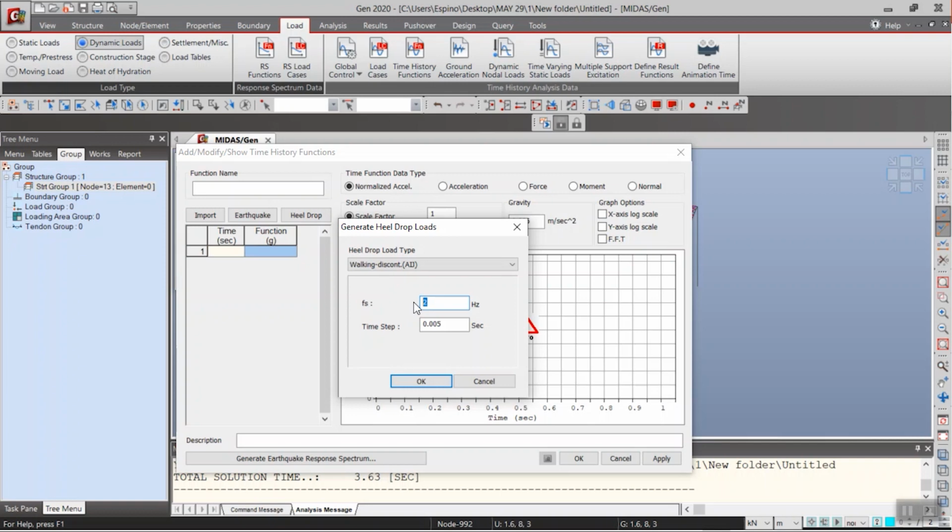This is because the vibration amplitude by resonance is increased when the two frequencies match or are at a multiple. Since the frequency of the floor is 3.9286, and we can consider it as approximately 4 Hertz, in order for resonance to occur, the frequency must be approximately 2 or 4 Hertz.